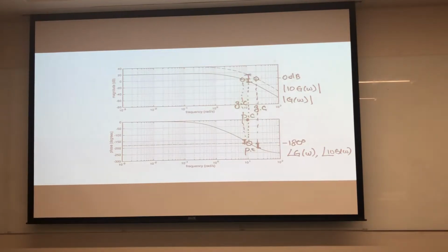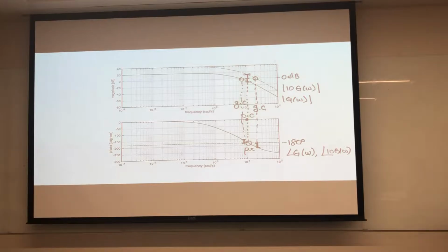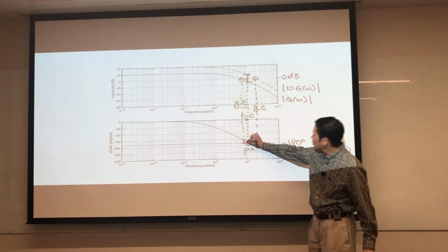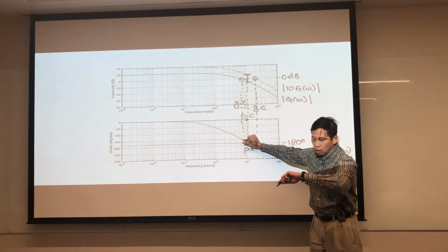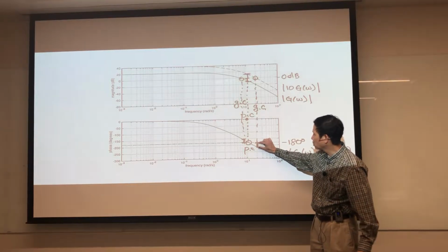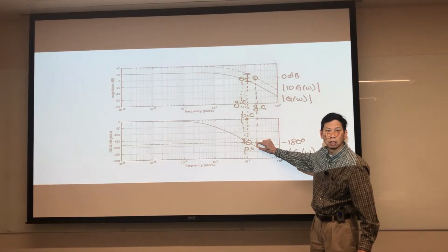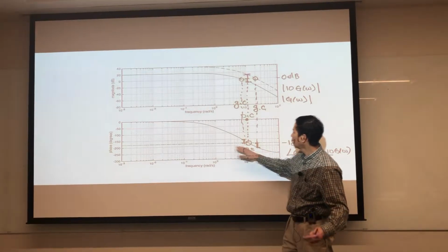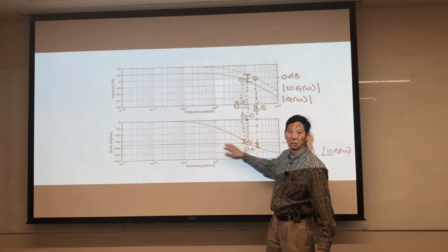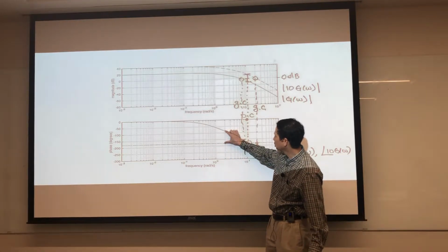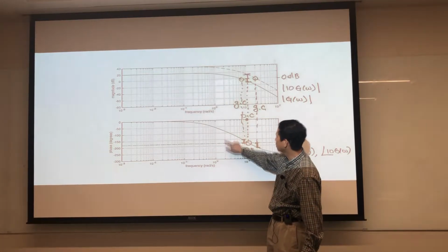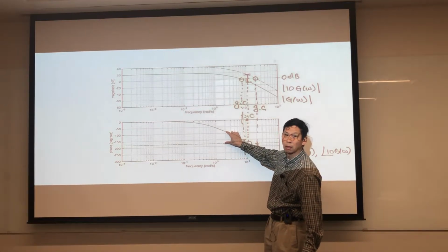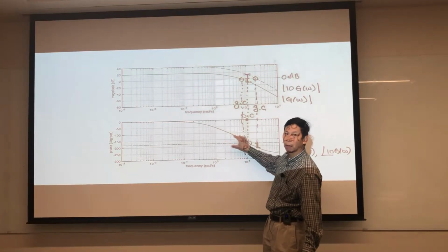So we will look at this plot and we'll say, what is the desired margin? Initially we started off with this margin. With proportional control, the margin became that. That's not good. So we had to look at this curve and say, what is my desired margin? I want to stay away from 180 degrees. So I got to pick a margin. Somebody says 60 degrees, so I got 60 degrees above that. That's my desired margin. We got to pick it.